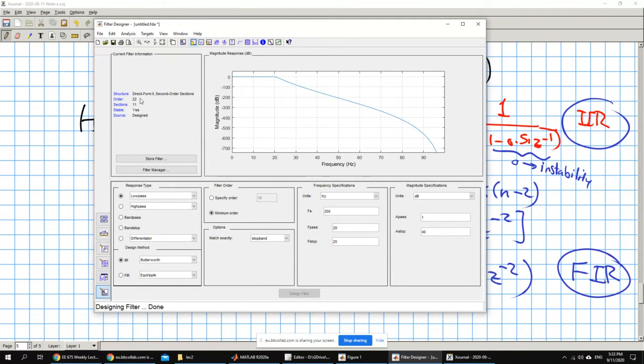On the other side, you can find some cases, which we're actually going to run into when we try to do the experiments, where the IIR filters might actually be unstable. When you try to design a filter that is really complicated, sometimes the IIR filters will not give you a good result. Okay, but you have to judge that for yourself. You have to try to design FIR filters and IIR filters and compare the outputs between the two so that you can determine whether you can actually use the efficient implementation of the IIR or not.